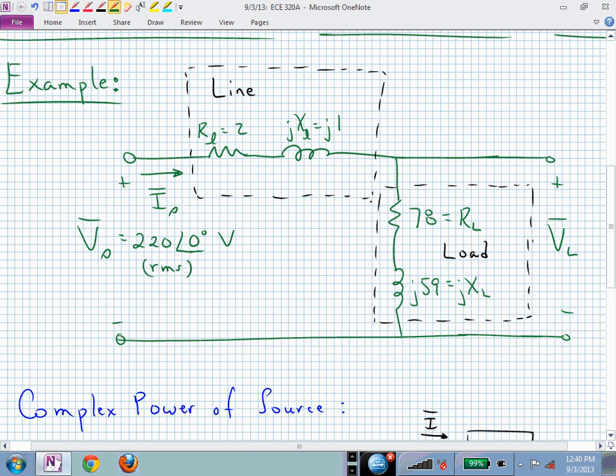Why is that? So I made a big deal about going into. If the current, as I've drawn it, goes into the positive before it goes through the element and then out the negative, then it's going into the positive terminal. In this case, what's really happening? I sub s is going into the minus, through the element, and then out the positive. It's not into the positive. Do you see the difference?